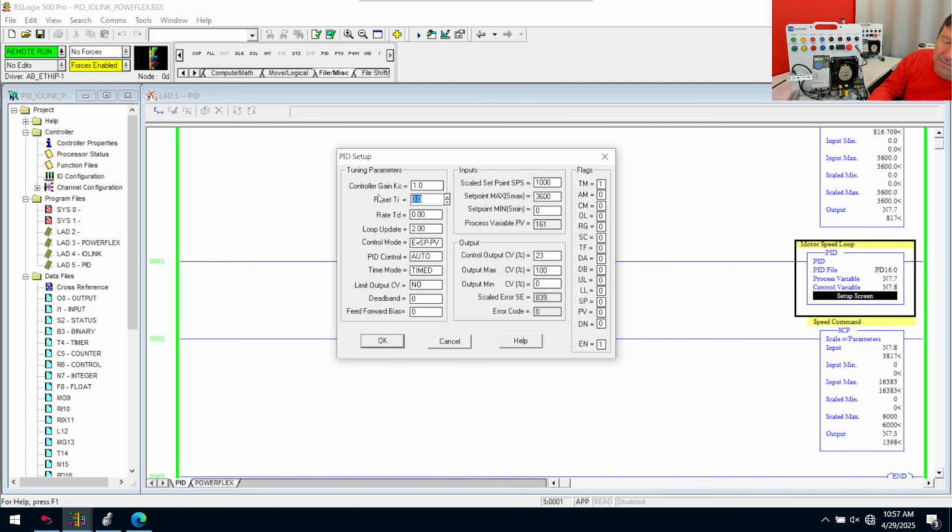So now we wanted to do some adjustment. Now I'm arbitrarily throwing numbers. I'm going to throw a 5 here. And now, every 2 seconds, this is adjusting. So it's slowly bumping our speed up. And it's going to slowly get there. I probably should have been a little more aggressive with my proportional. In fact, let's do that. Let's go ahead and change that proportional to 5.